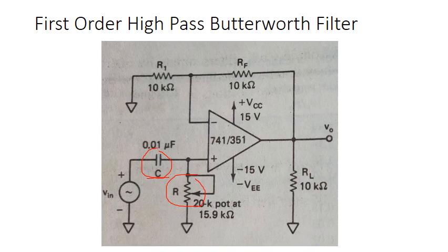Resistor R1 and RF determine the gain of the op amp. Since the input is connected to the non-inverting terminal, the gain AF over here is determined by R1 and RF, which is given as 1 plus RF by R1. The output voltage V0 is gain times, that is AF times this particular voltage at this point.